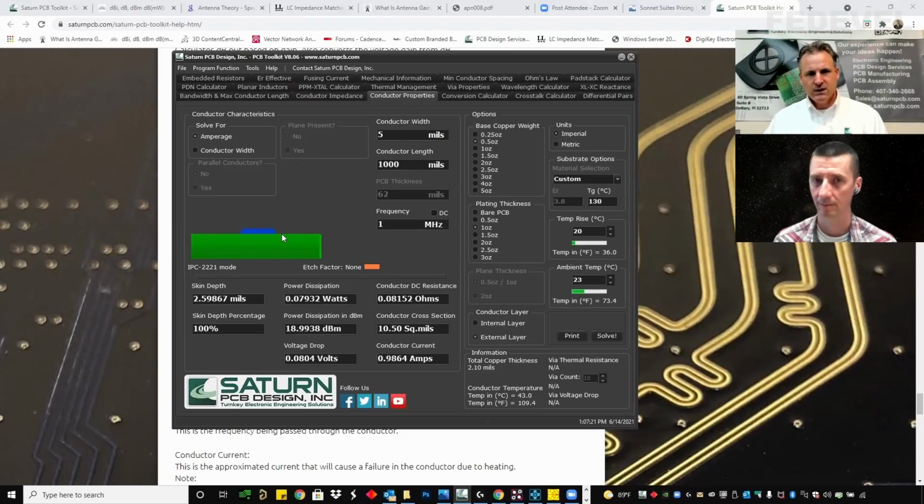It's measurements. Somebody took a thermal camera and measured conductors at certain ambients with certain current flowing through them. Well, what they found is that internal traces can actually handle slightly more current than an external trace because the FR4, they actually used a polyimide, 70 mil polyimide, but it could actually handle more current than the external trace because the fiberglass was such a good conductor, a good thermal conductor.